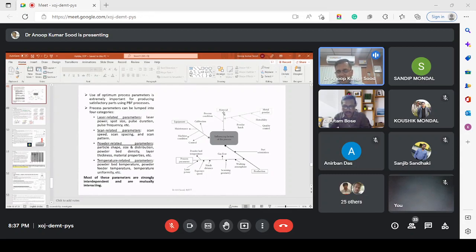And then the entire powder layer is not at a constant temperature. The region near the laser or the electron beam source is at a higher temperature compared to the rest of the powder bed. And there is continuous melting and remelting of the already solidified layer taking place. That is also inducing defects in the part. So we may not get a homogeneous microstructure, nor homogeneous properties. So anisotropy will be there in this part.